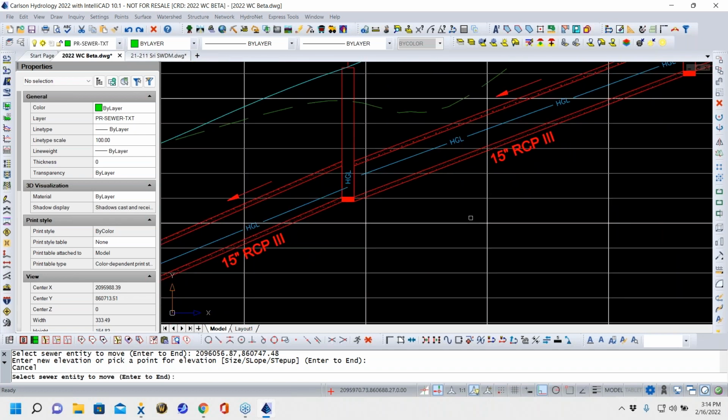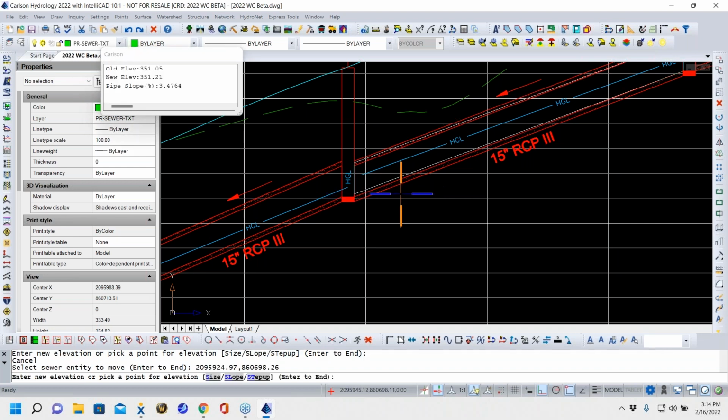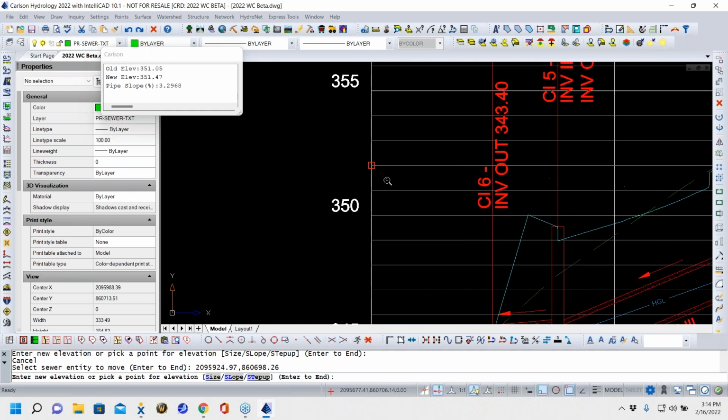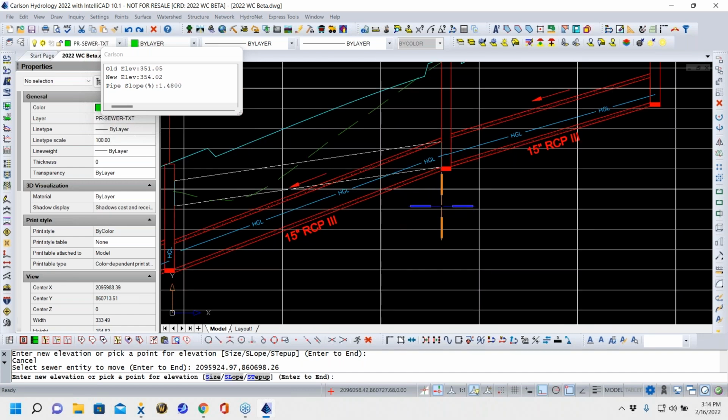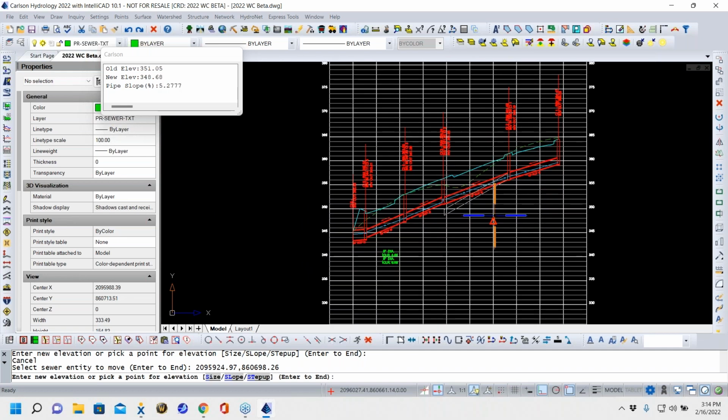Now, let's look at this. I need a 2/10 drop, even though I told it, for some reason I don't have it, but let's go ahead and make it. The cool part about this is that if I drew the grid at a half-foot interval, and I go perpendicular to a polyline, that is an even elevation. So I'm snapping to even elevations and designing in this profile view.